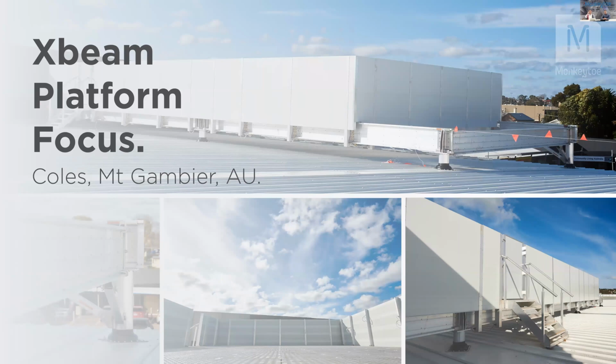As it came out, there were massive cost savings in fixing it back to the portals, and obviously looking at the steel option, the steel was not an option due to the extra loading that was going to be loaded up on those portals. So it came back to the Xbeam being a nice lightweight solution which wasn't going to load up those portals too much.